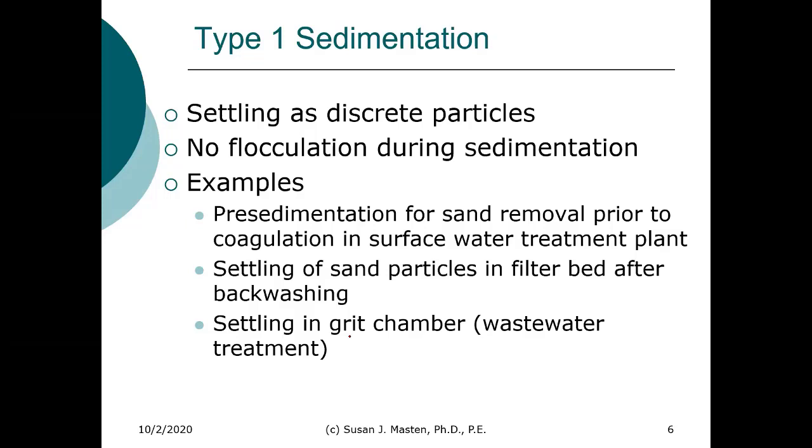In a filter bed, we'll talk much more about this, but we'll talk about backwashing. So basically, you pump water up through the filter, you fluidize the bed, that releases the particles, and then you allow the sand to settle again. As the sand particles settle, they're settling by type 1 sedimentation. They're settling as discrete particles.